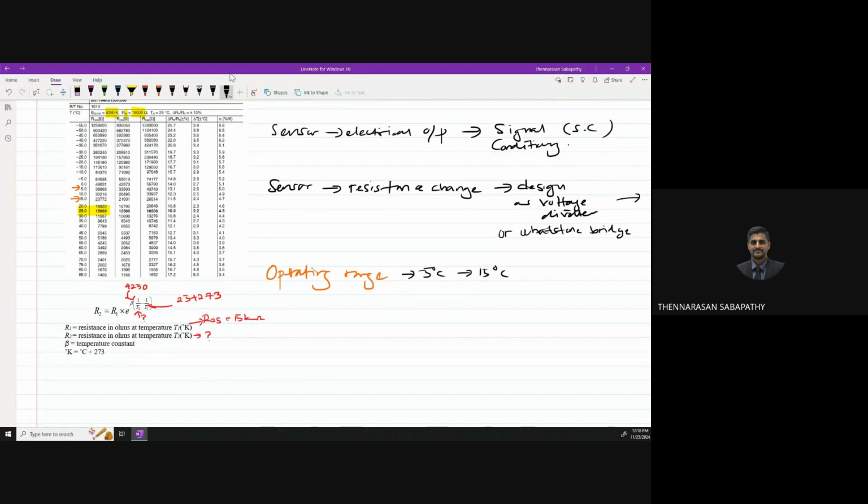I don't want to use R2 like that day, so that we don't get confused with the R2 and R from the voltage divider. So let's call it RNTC. RNTC equals 15K times exp of 4250 times (1 over T2 minus 1 over T1).